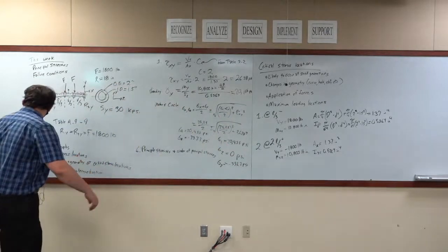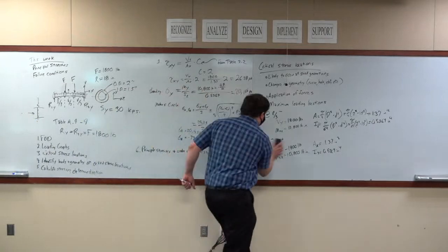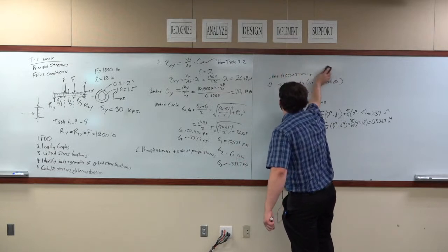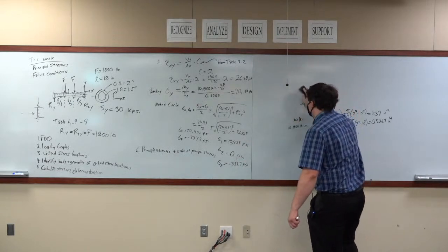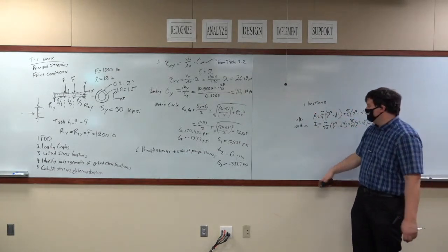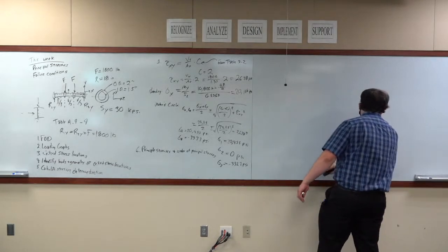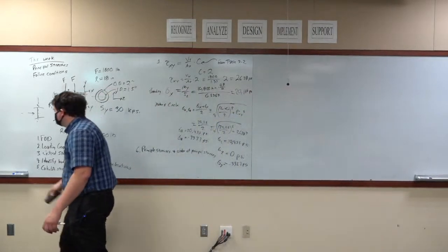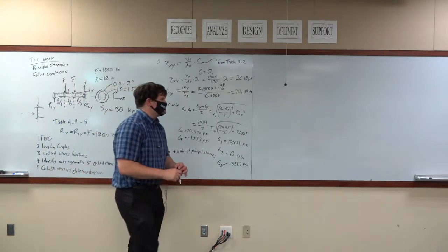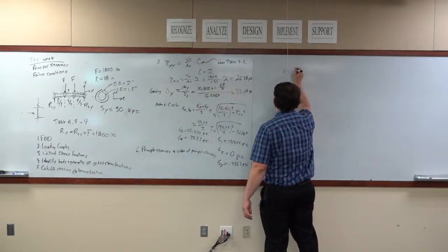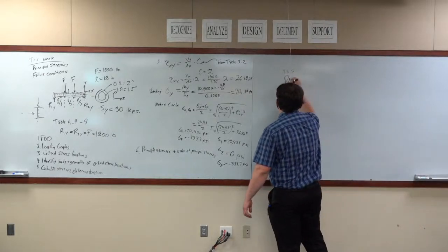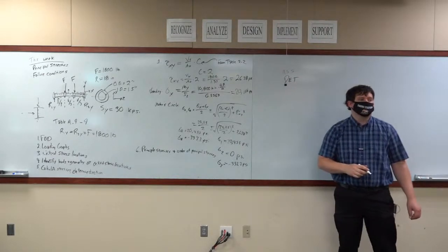Okay? Now, taking the principal stresses, the goal of this is we want to know what our factor of safety is. We are looking for one number. We have spent all class looking for one number. There's a number of different methods you can use to find that one number. You can use the maximum shear stress theory, MSS. This is a conservative estimate. You can use the distortion energy theorem, which we are going to use.